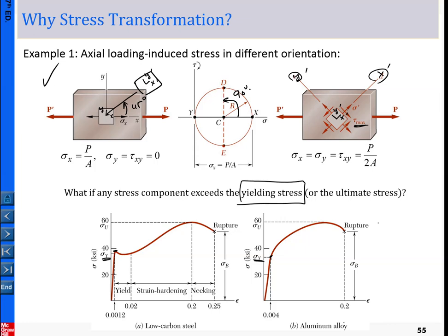Any material under elastic deformation will be able to recover back to its original shape as long as the loading is in the elastic regime. If the loading is so big that it is beyond the elastic regime, that means beyond the yielding stress, then the material will be deformed permanently. And very likely, once the material is in the plastic domain, long-term fatigue will cause the material failure.